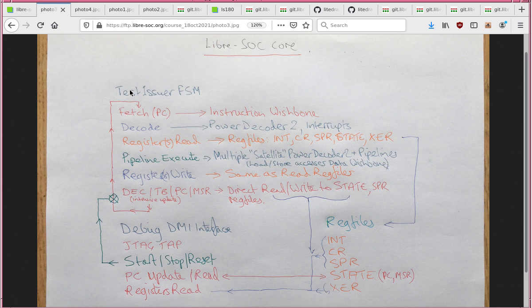So what we did was we went through the standard fetch, decode, issue, and execute phases, but did so one cycle at a time. Pipelines will run all of those in overlaps. Whereas this does a fetch stage, waits for that to complete, then passes the fetched instruction to the decode phase, and waits for that to complete. On decode, it's able to identify what the instruction is, so it can then read the registers that are needed.